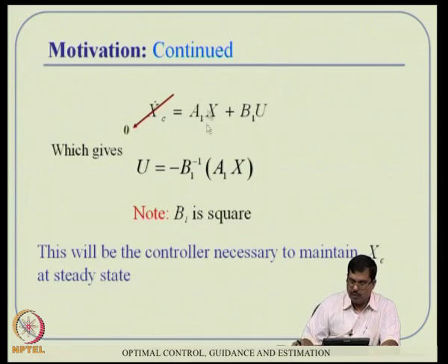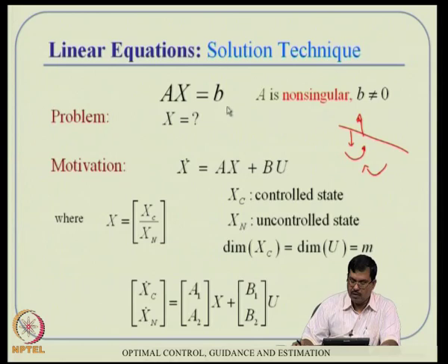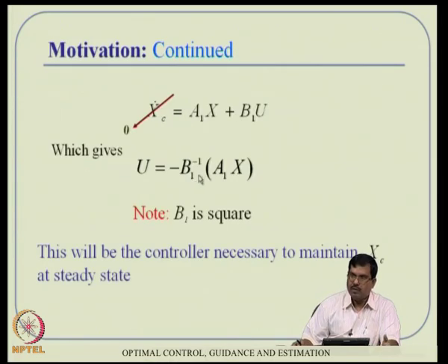Now, this A1 of x is nothing but our b, if I go back to that, and this A y is nothing but b1 actually in this case. So we require this kind of solution, efficient ways of getting solutions and things like that. Remember, this control has to be applied online also. That means we cannot afford to have a lot of computational time wasted on computing this V1 inverse. We do not want that. Okay, so we want an efficient way of finding this V1 inverse.